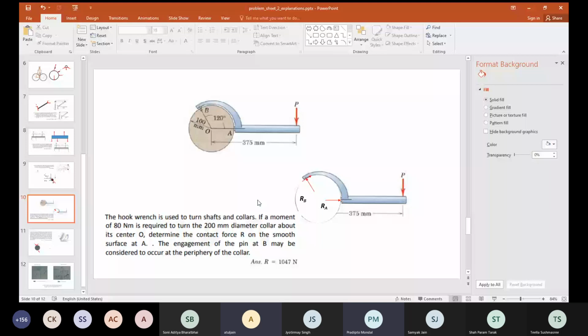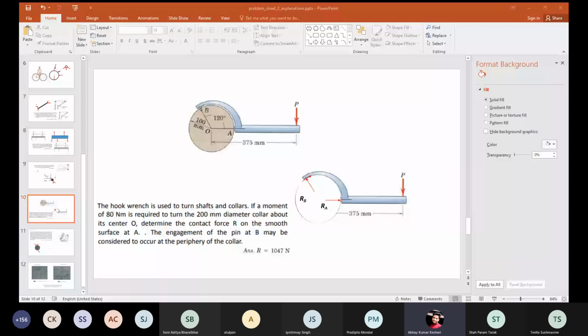For finding tangential force, can we draw the free body diagram of the collar, and then the torque will be provided by the tangential force, and if we equate it to the net torque required, will the answer be right?